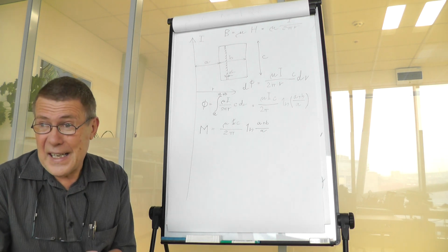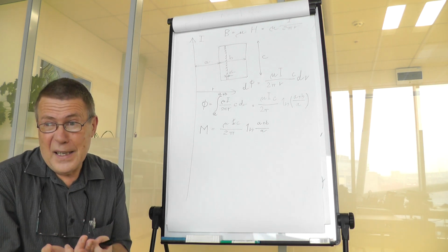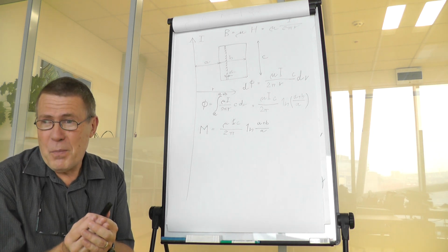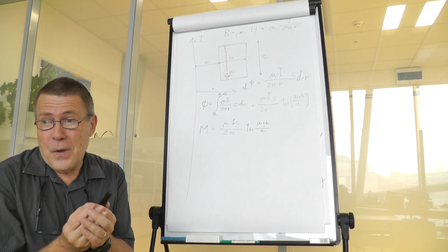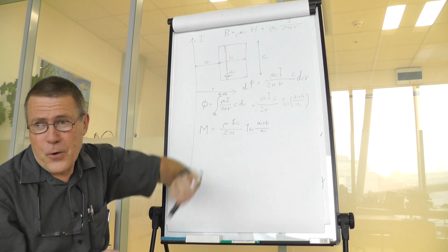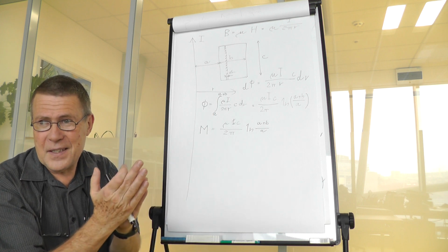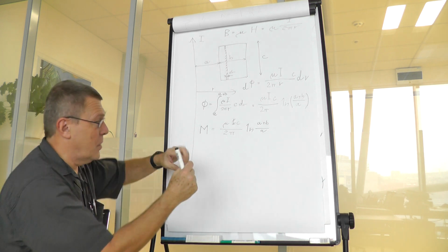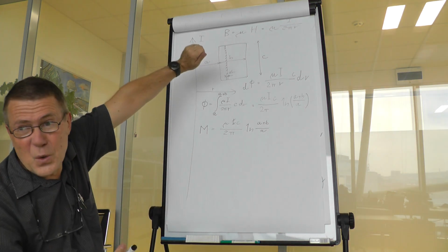What can you do against that? Well, the first idea, important for example even for your measurements, is that if there is some way to the load and a way back from the load, and there are two conductors, the simplest way is just to twist them together.